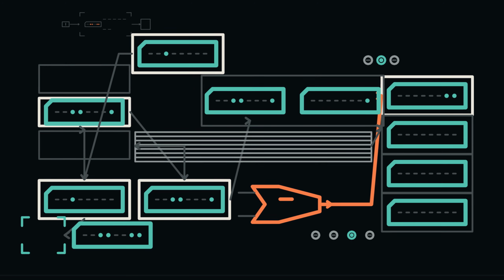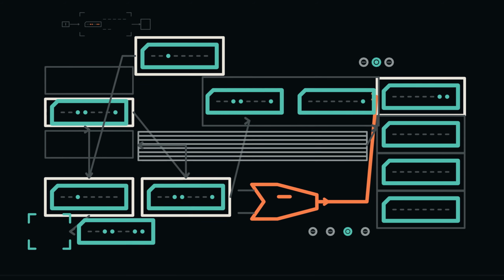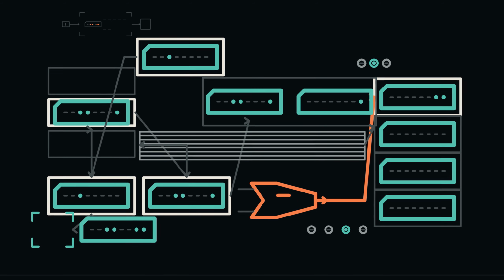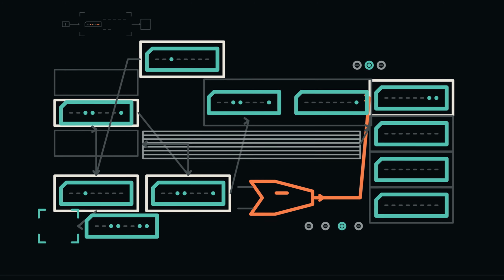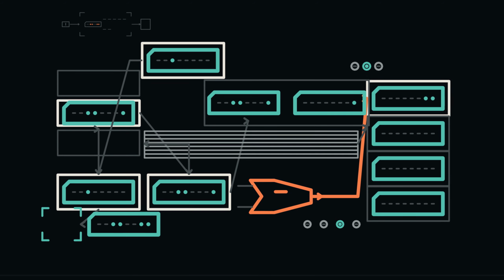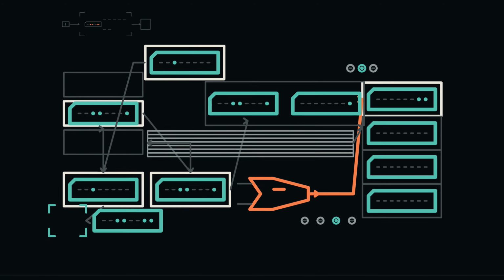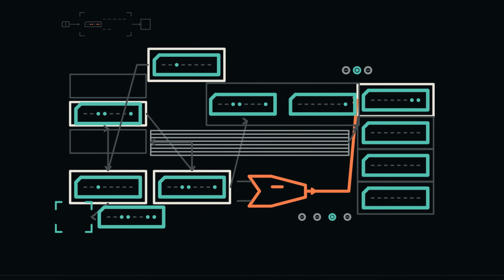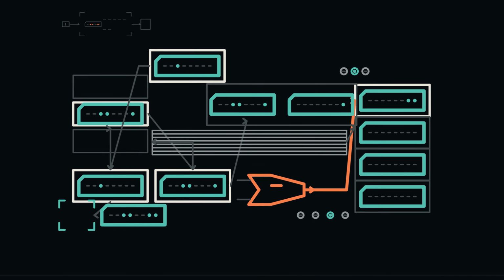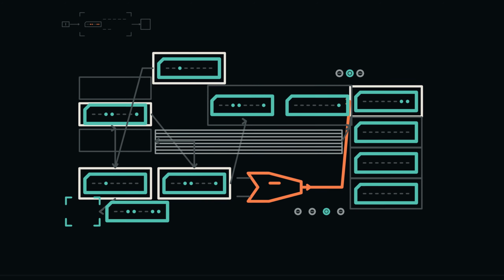The address decoder gives every address exactly one destination. Most addresses select ordinary memory. A reserved upper region selects device registers instead. This is how input and output join the machine without a second kind of instruction. A load from a keyboard register still obeys the load contract. A store to a display register still obeys the store contract. The selected address changes which receiver stands behind that contract, not the meaning of loading and storing inside the processor.